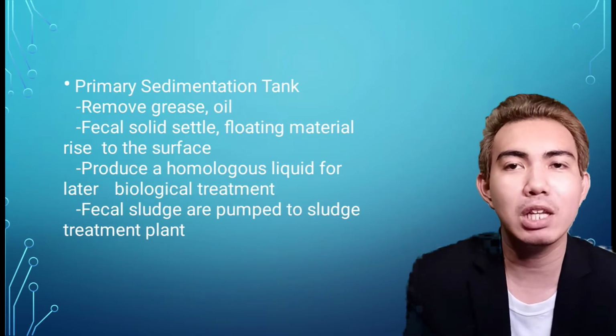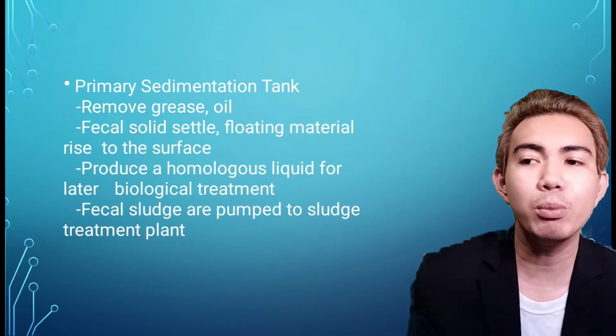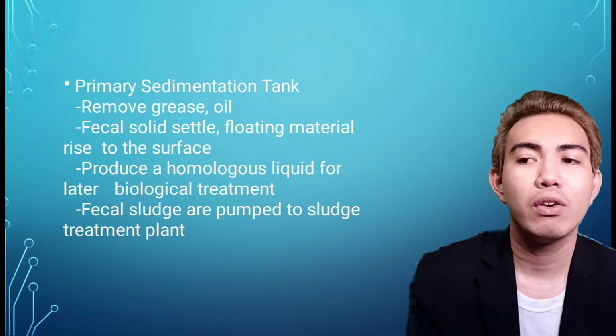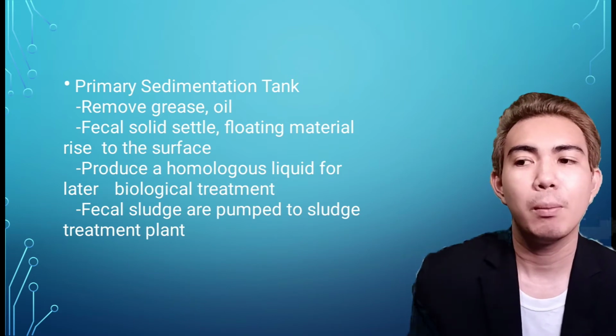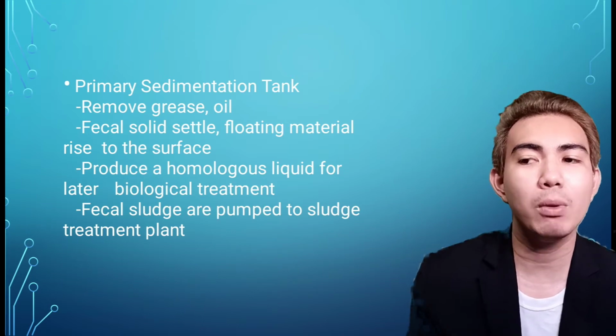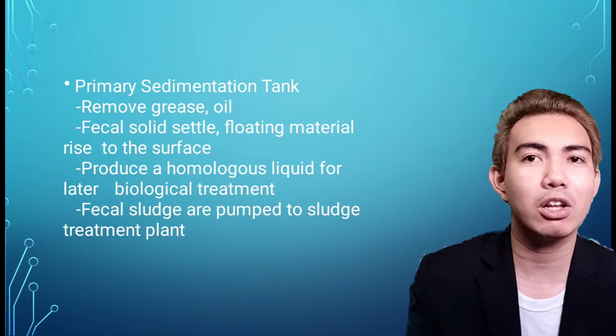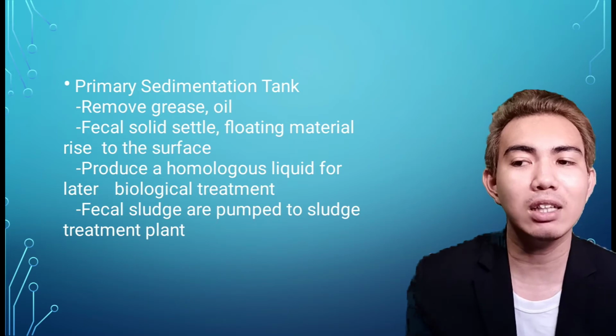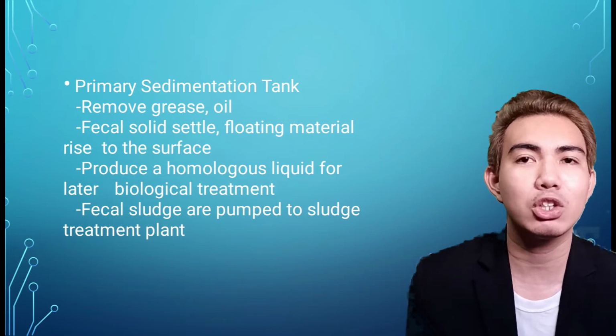We have the primary sedimentation tank. Remove grease, oil, fecal solids settle, floating materials rise to the surface, producing a homogeneous liquid for later biological treatment, and fecal sludge is pumped to a sludge treatment plant.